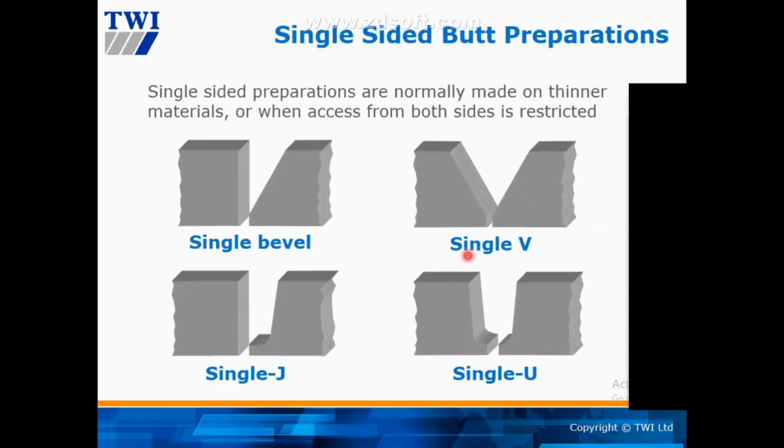When the thickness increases, maybe 10, 20, 30, 40, depending on the drawing from the design, we can have single bevel, one side bevel, or maybe single V, both side bevel.